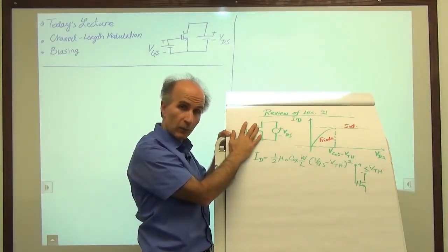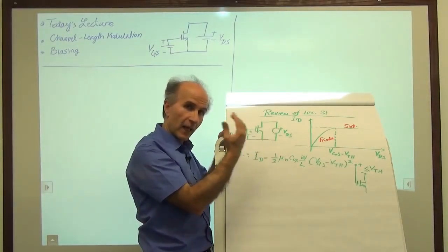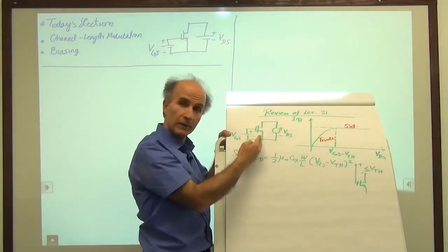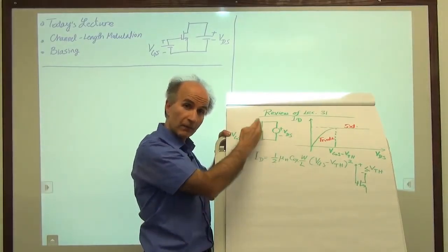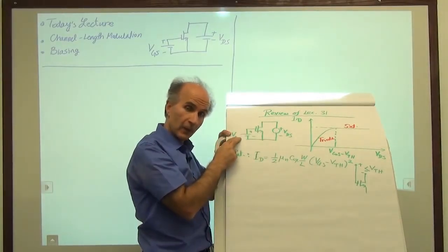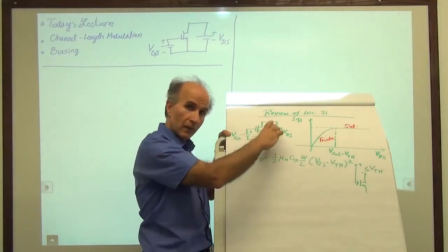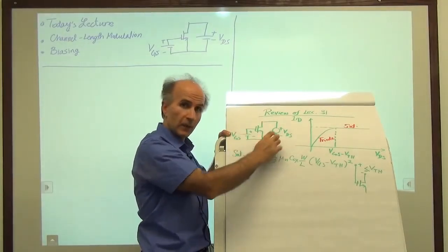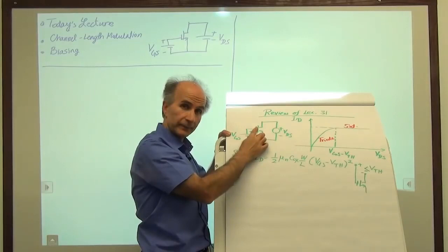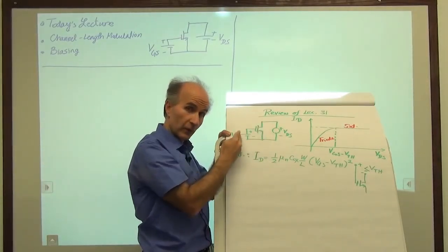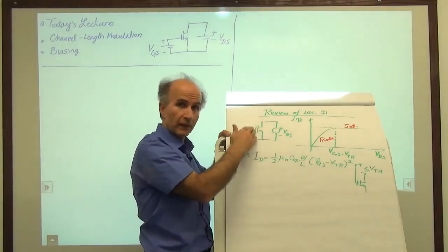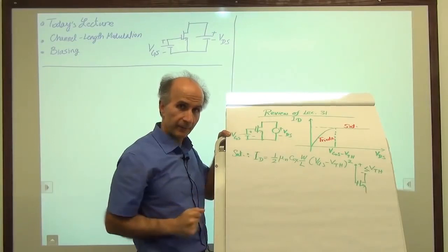So that's good. That's what we were hoping to achieve when we built a little amplifier and then said, can we build a voltage-dependent current source? Indeed, we have a current source. And it's voltage dependent because its value depends on this guy. So it's important not to confuse this voltage with this voltage. This is a current source as far as these two terminals are concerned because when this voltage changes, this current doesn't. But it's a voltage dependent current source, meaning that if I change this battery from 1 volt to 2 volts, I get a new current source, and that new current source is also constant.